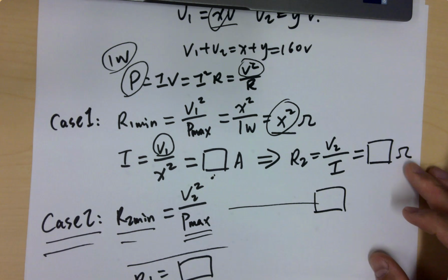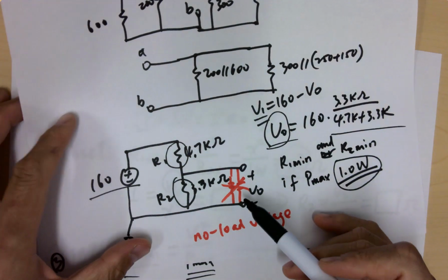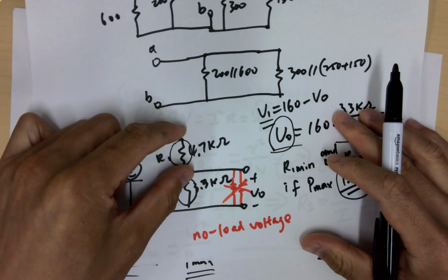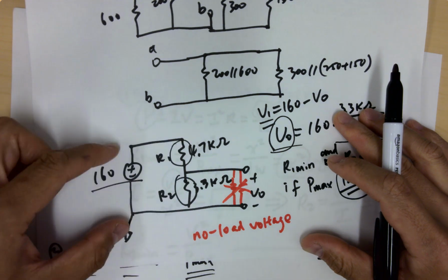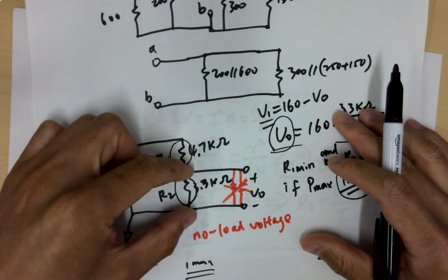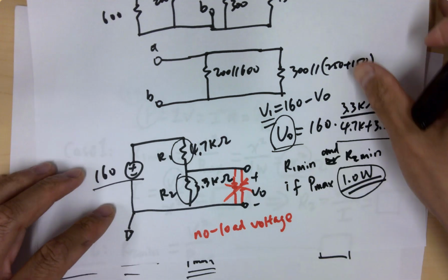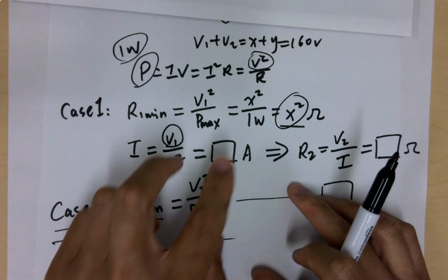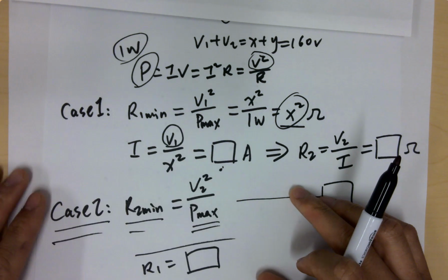And because the voltage doesn't change, which means the voltage ratios don't change, you can compare which is taking more voltage. It's just a voltage divider. If one is taking more voltage, it must have a higher resistance. So if you come back to this calculation, you got 2 sets of R1, R2. There must be just one of them that satisfies this condition.